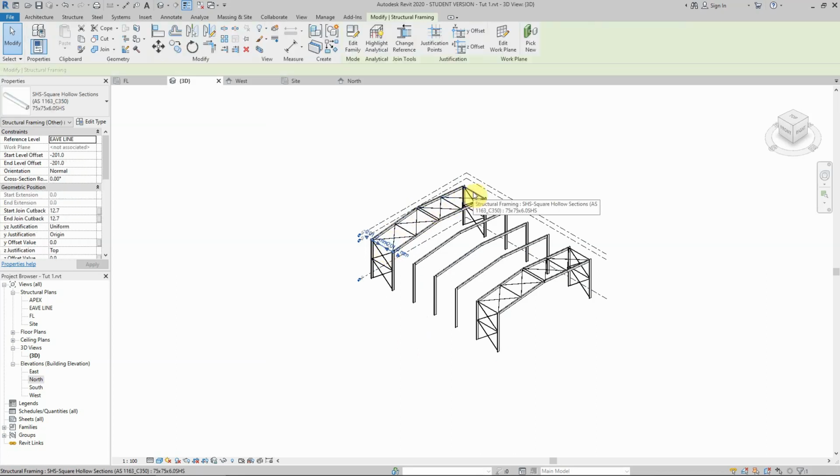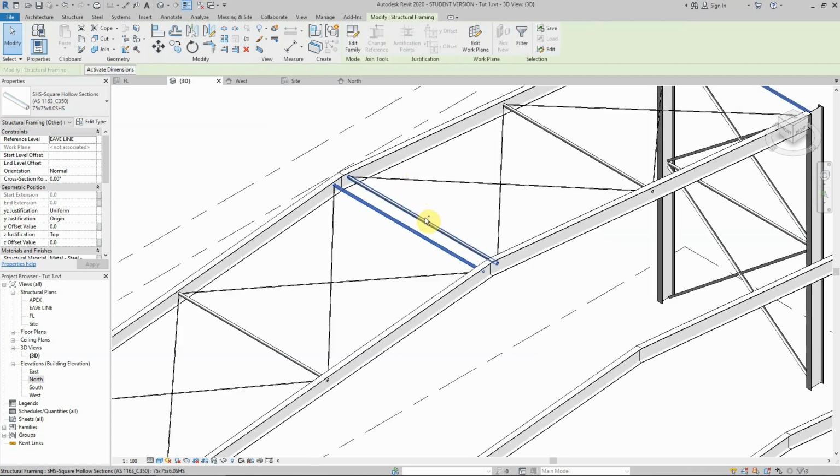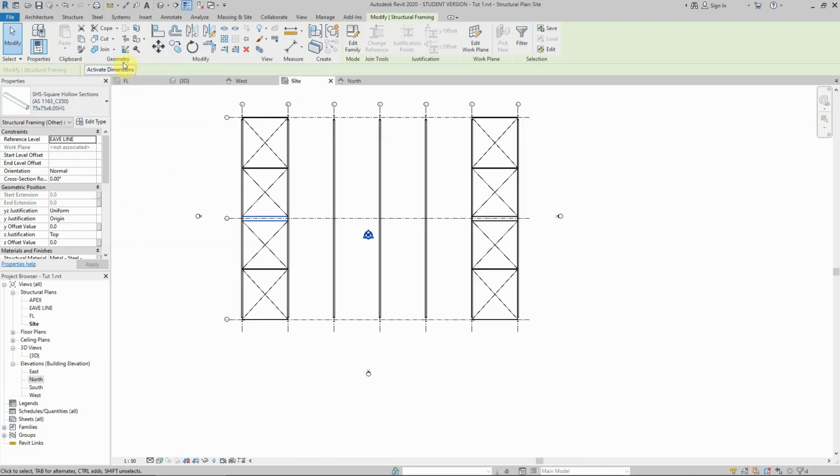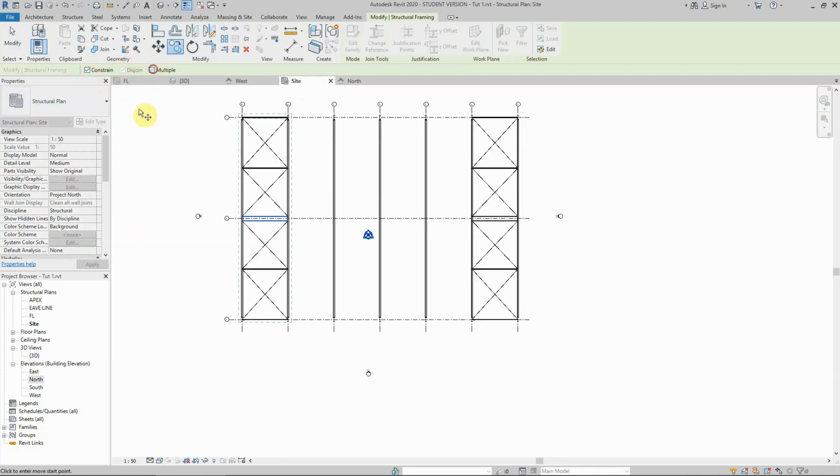two edge struts plus the two big ones, those ones here, to all frames. Simply those will work as separation members between the frames to keep the frames spaced at the right spacing. So if I just select them from here, and I can go to the side view and choose copy, make sure multiple is selected, I can just copy them to all locations, all the frames. That's done.